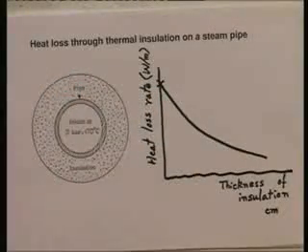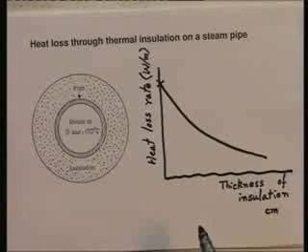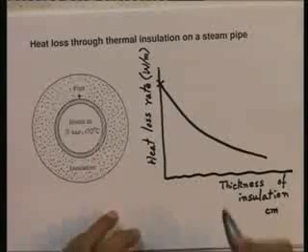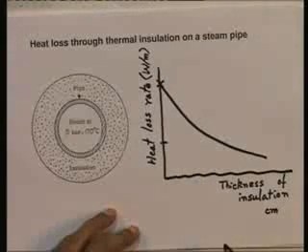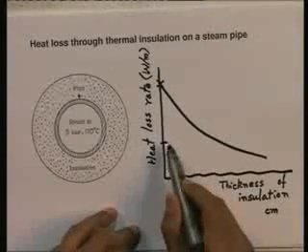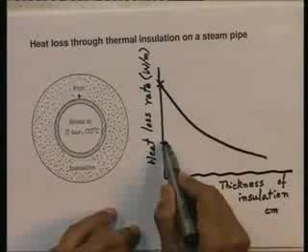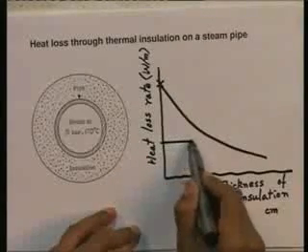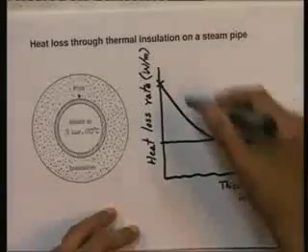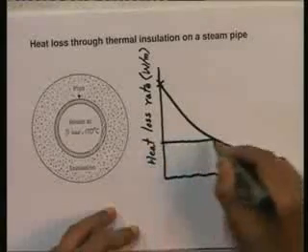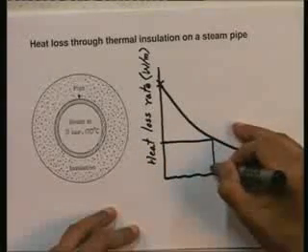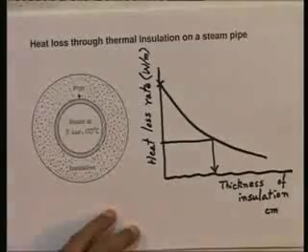Now, the problem before the heat transfer engineer, who is to design this and decide what thickness to put, is the following. He is told, restrict the heat loss rate to a particular value, let us say given by this, as I am marking here. So, find the thickness of insulation to restrict the heat loss rate to the value specified here, in which case, having done this calculation and got this graph for a particular insulation that he is using, he will go horizontally, then go vertically and say this is the thickness of insulation needed.